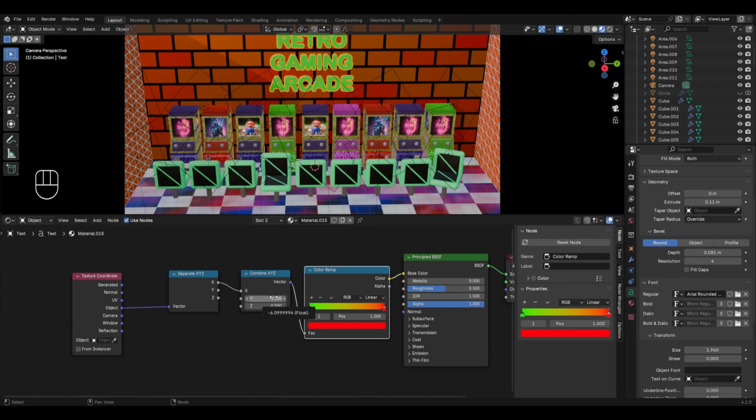So basically, at frame number 1, we'll set the color as red by inserting a keyframe for this particular value of the Y parameter, and then after moving some frames, we'll show a change in color to the green color by inserting another keyframe for this value of the Y parameter. So to do this, I'll first change this value to positive 6, which is giving us the red color. So right now, I've adjusted the value of this parameter to 9.5,